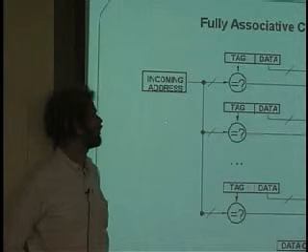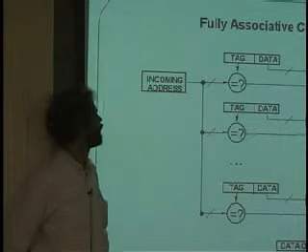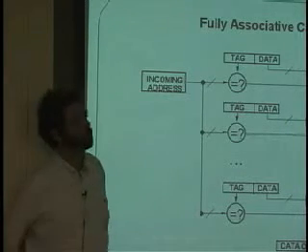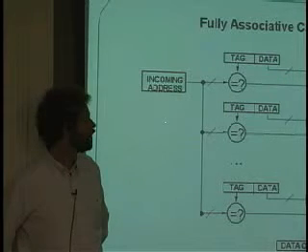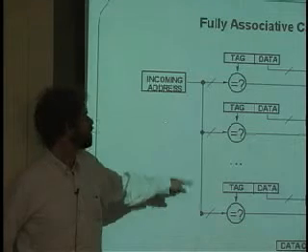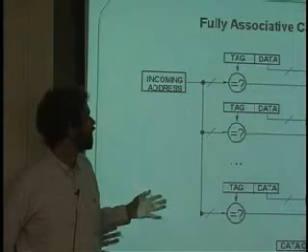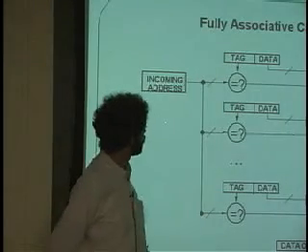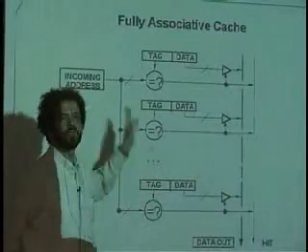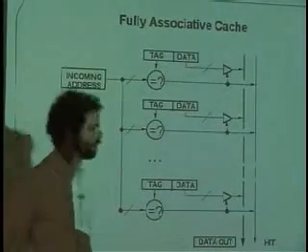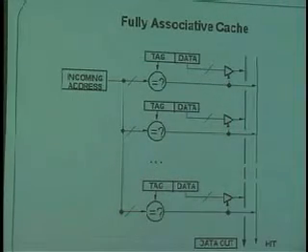And we're letting the memory itself figure out which row has the match. Okay. And this is a really great cache. What's nice about this kind of cache is that any particular address in the slow memory can be cached in any of the locations inside of here. There's no constraint in any way saying that address 100 needs to be in this row. It could be in this row or that row or the other row. It really doesn't care. We haven't talked about how it figures out what to cache and what to throw out and stuff like that yet, but we will get to that.